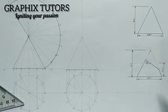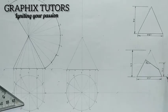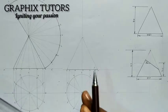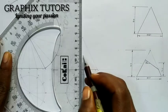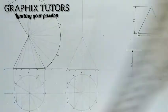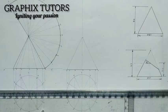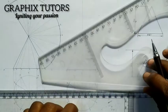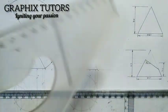Now if you recall, at a height of 20, my cone is being cut at an angle of 30 degrees. So I'm going to measure 20 from this point here. This is 20, right? At that point is 20. And I'll place my T-square on my drawing board. I'll take my set square. When it is like this, it is 30 degrees. So I'm facing it in this direction.